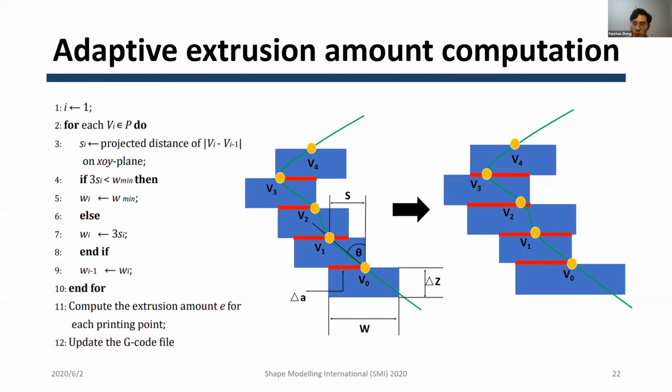We traverse every printing point from the bottom layer to the top layer and keep the line width of the current point and previous point of the neighboring layer equal, expanding or reducing their width simultaneously with the same scale until the proportion of overlap reaches 2 divided by 3. Based on the range of parameters, we can deduce that the threshold we used before is 15.7 degrees.